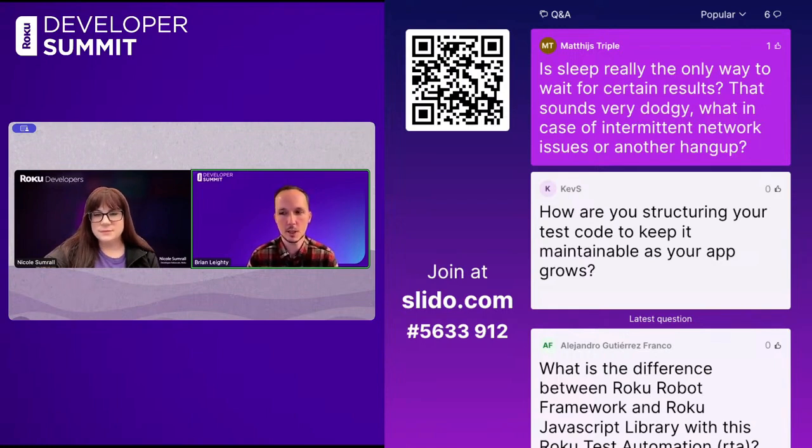But it didn't matter what speed it ran at, it was still just waiting for the observer to kick in. So whenever possible, either use observers or the other thing we'll start doing, which is using a while loop and calling get value repeatedly on the device. Both of those work much better than sleep. And yeah, I try to avoid sleeps as much as possible.